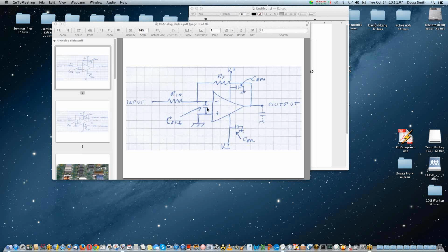We have a question that says, we have tried using grounding rings around the op-amp. What is your experience and opinion on those? These are in reference to high impedance nodes. A grounding ring. Well, one question is, is it a multi-layer board or a two-layer board? A lot of times op-amps are on two-layer boards because they're perceived to be low frequency. So I haven't seen that. And if you had really high impedances, that would help reduce coupling to nearby other things on the board. I've never felt the need to use that, though.